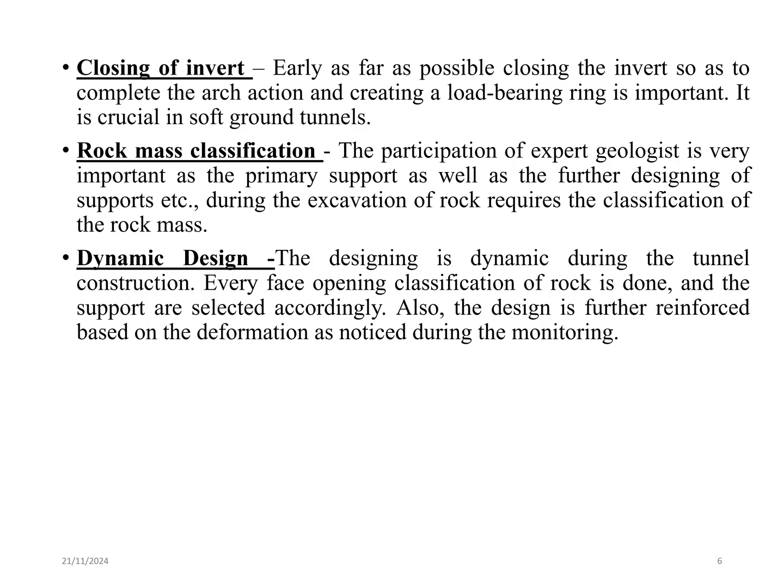Lastly, the seventh important principle is dynamic design. The design is dynamic during tunnel construction, with support selected based on rock classification and reinforced based on observed deformation.